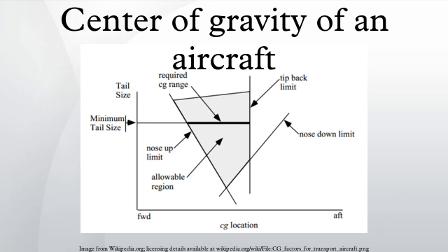The helicopter will have a nose-low attitude, and the pilot will need excessive rearward displacement of the cyclic control to maintain a hover in a no-wind condition. In this condition, the pilot could rapidly run out of rearward cyclic control as the helicopter consumes fuel. The pilot may also find it impossible to decelerate sufficiently to bring the helicopter to a stop.